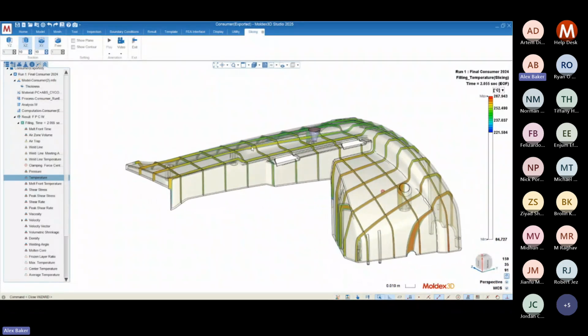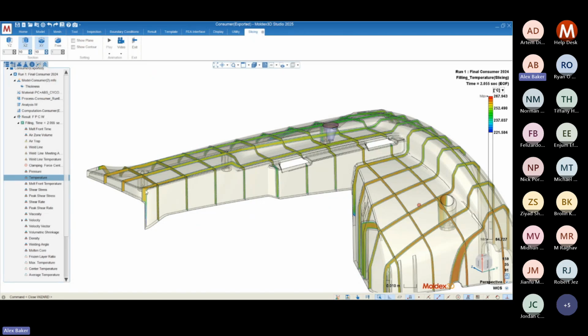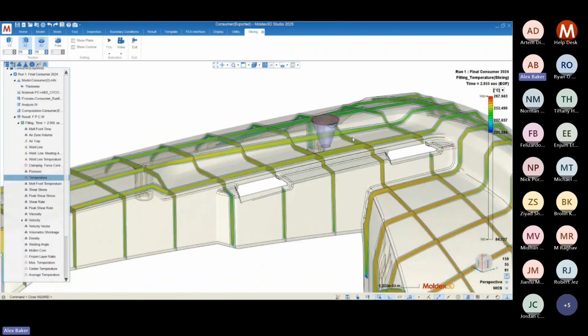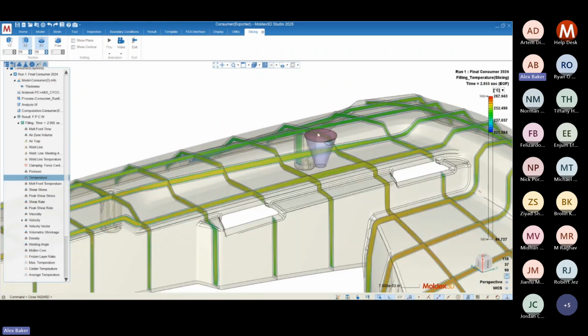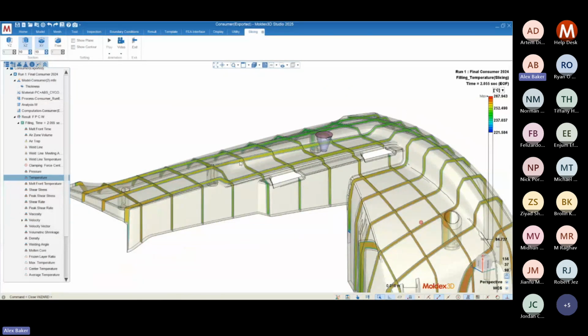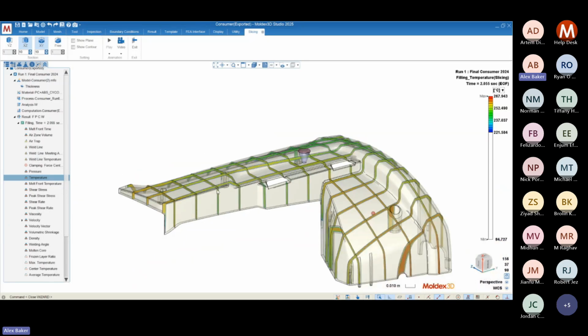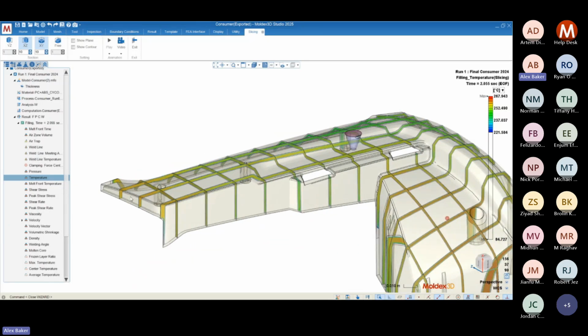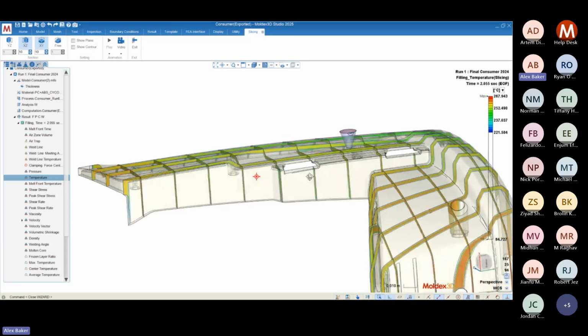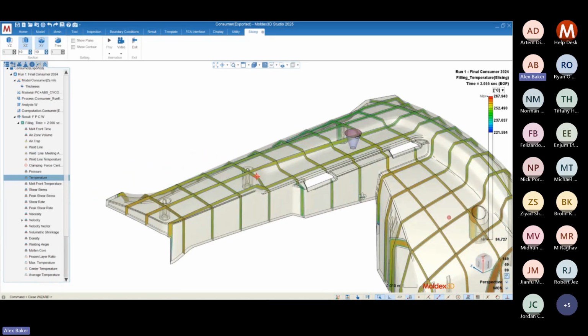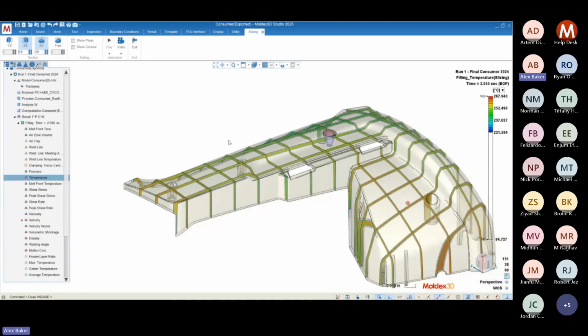And actually, in this case, we can see that the temperature at the end of fill is hotter, or higher, than the gate location, which is kind of counterintuitive. You would think that the heating source is at the melt entrance and that heat, that energy, should be releasing out into the mold as the material flows, which means that the material's temperature should decrease over the length of fill. But actually, the shear heating effect in this case caused the temperature to increase over the length of fill, which is likely a proponent of the filling speed that we elected to use in our process.